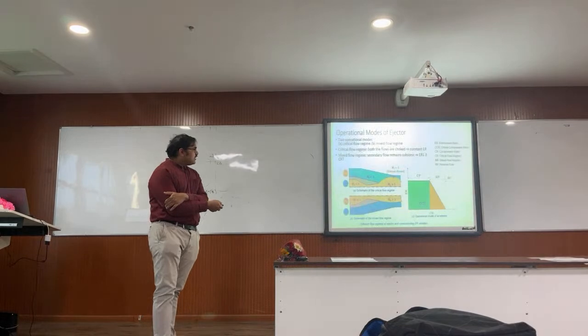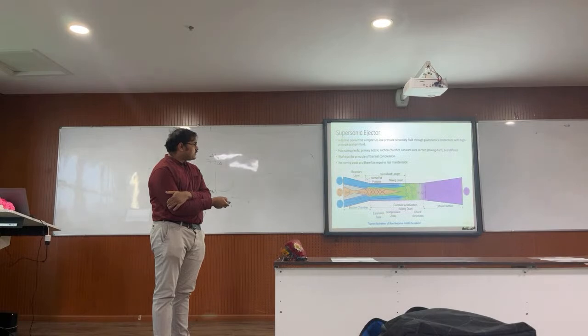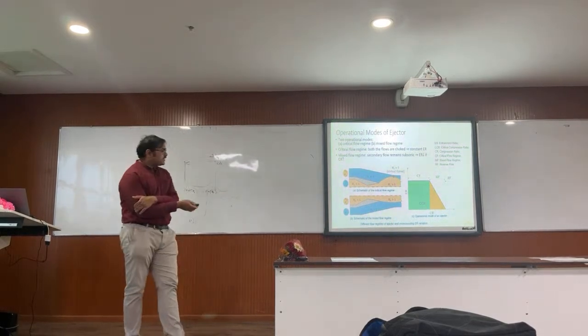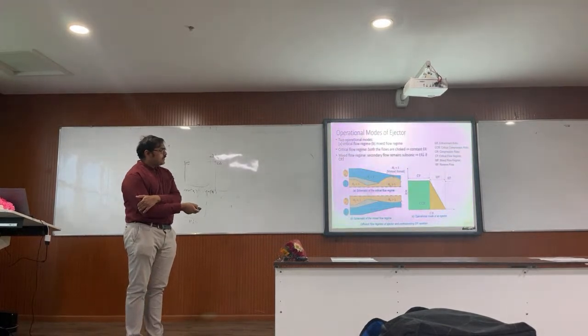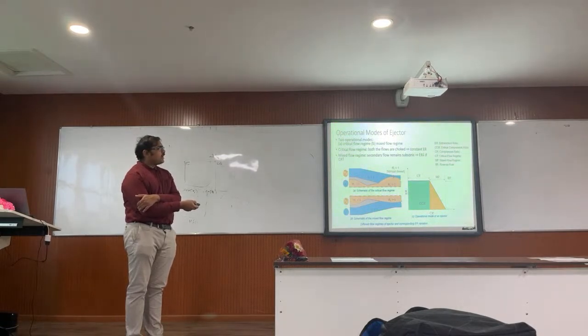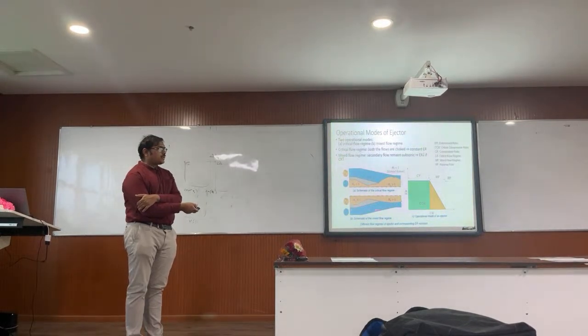And it's used in several applications. A large number of applications use these supersonic ejectors. And these supersonic ejectors also have two regimes. They have what is called the critical flow regime, and what is called the mixed flow regime. In the critical flow regime, the supersonic jet produces a virtual throat for the secondary flow, and it chokes it over there. While in mixed flow, the secondary flow remains subsonic.